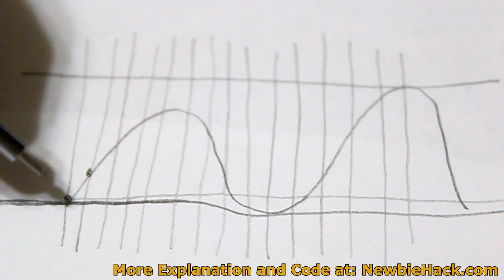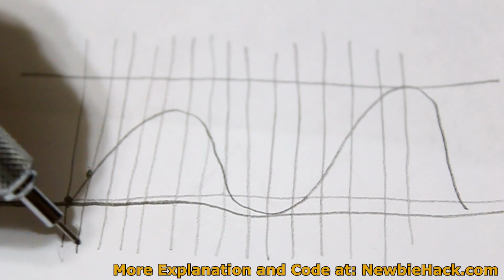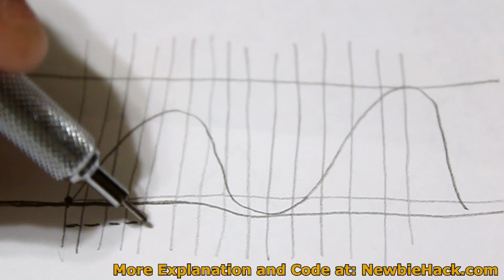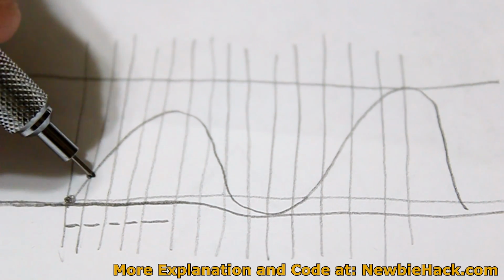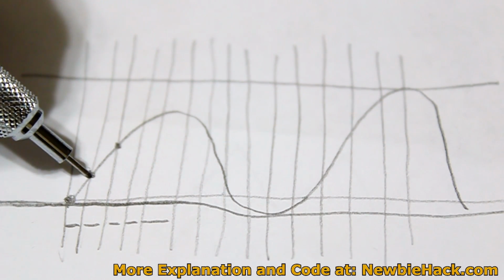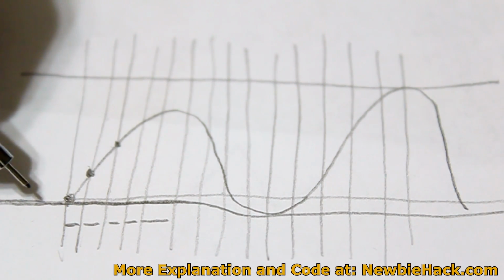And in this waveform, to create the voltages that we need to match the waveform, we would have the periods, just like we would in the PWM. This would be one period, and all these periods would be the same, constant. It would be the same time frames, and we would have to plot the voltages and determine the duty cycles for each one of these. So let's figure out these duty cycles.